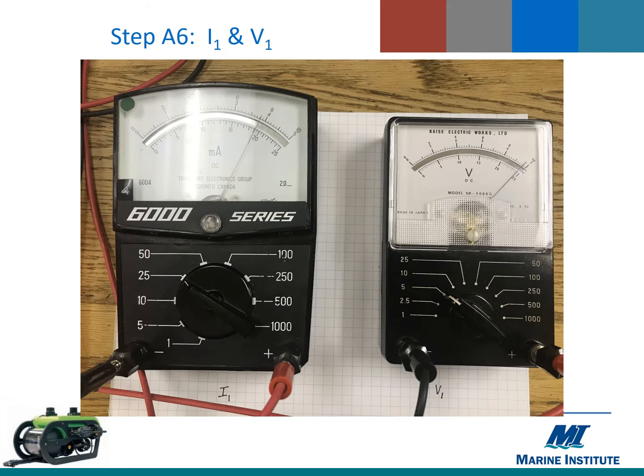Okay, so the close-up of the meters for I1 and V1. Now you notice if we start with I1, I1 is on the 25 milliamp scale still. And so again, that means 25 milliamps is the maximum measurement here, so the 25 scale. And you'll see again that that's really close to 19, might be a shade above, but we call that 19 milliamps. Now for the voltmeter, this one is a little interesting because if you look at this one now, we have moved to the 5 volt scale, which means the maximum measurement over here represented by full scale deflection is 5 volts.